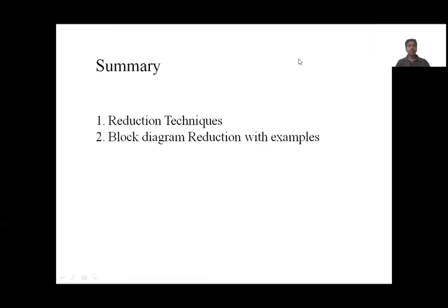Before concluding this session, let me recall what we have learned in this video. In this video, we have learned different reduction techniques, like if the blocks are connected in cascade or parallel, and feedback loops, how to reduce them, and different ways of arranging the summing points before and after the blocks, and how to move the takeoff point from before the block to after the block, and after the block to before the block, and various shifting and rearranging of different blocks to reduce the overall block diagram.